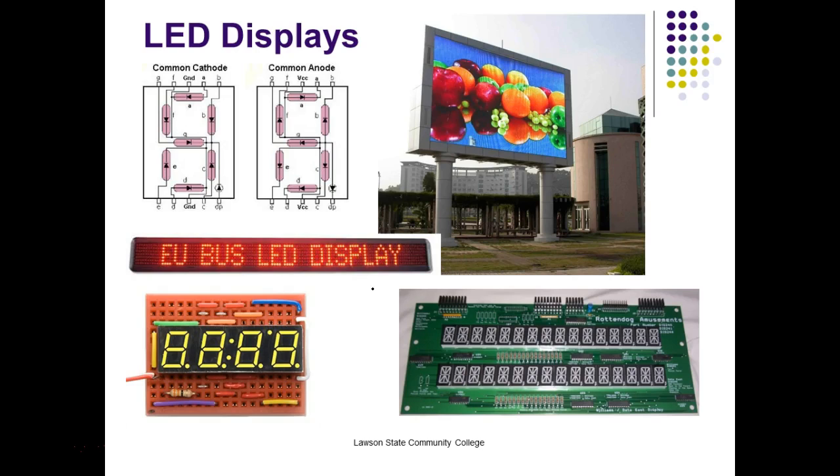Now it's not LEDs, but it works on exactly the same principle. So we see 7 segments in here, and we can display. So these guys work really, really well with displaying numbers, right? You understand that? Display characters. We could do sort of a Y. We could do sort of a T. Can't do an X, right? Can't do an O because an O would be considered to be a 0. Normally if they do an O, they do just the bottom 3 segments.